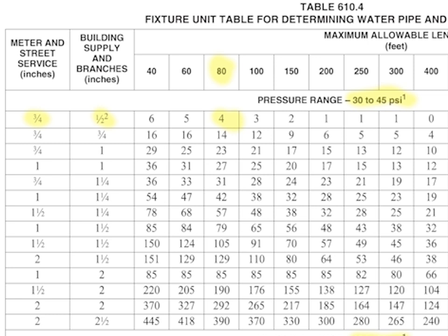of 1/2 inch. Had we done a trunk and branch, we would have needed to add each of our fixture units, and that would have driven us to 28 units for the cold fixtures. This would have resulted in a much larger 1¼ inch trunk pipe through the house.